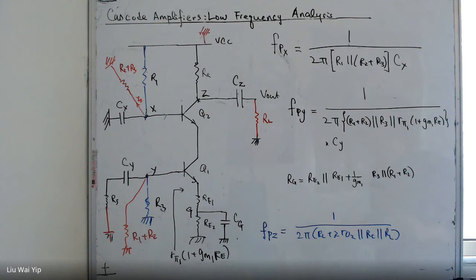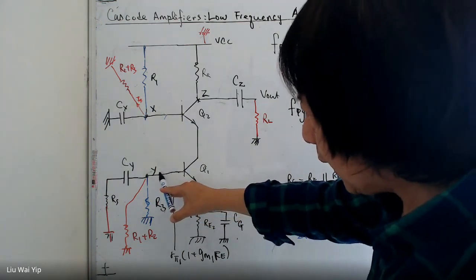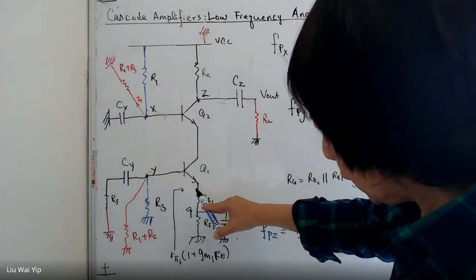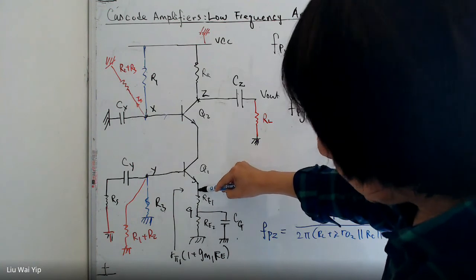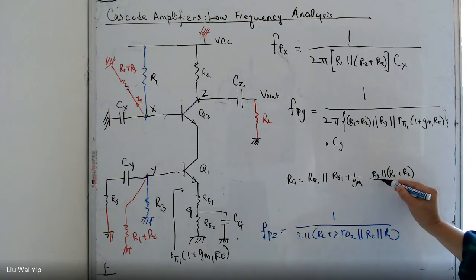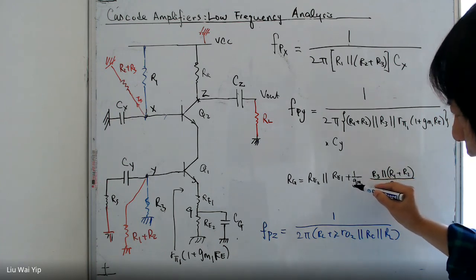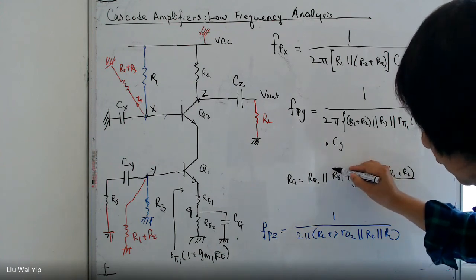Now this is not enough because the resistance here is in another environment under IB. You have to move to the environment where the current is IC. So what we can do is divide it by beta. Plus GM1 plus this one, which is this resistance here.